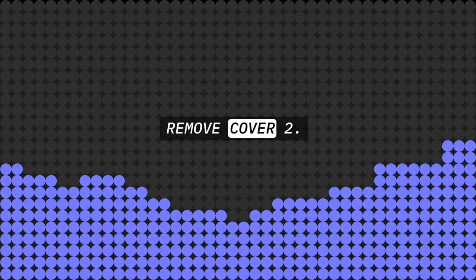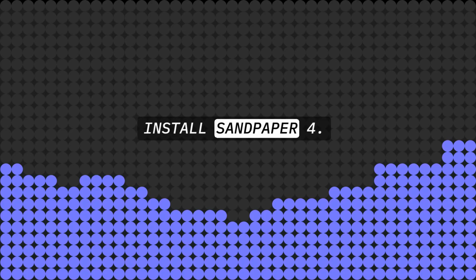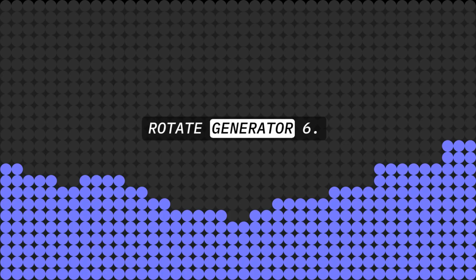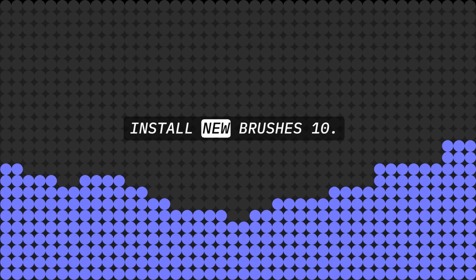1. Remove cover. 2. Remove brushes. 3. Install sandpaper. 4. Install new brushes. 5. Rotate generator. 6. Remove brushes. 7. Remove sandpaper. 8. Blow out generator. 9. Install new brushes. 10. Install cover.